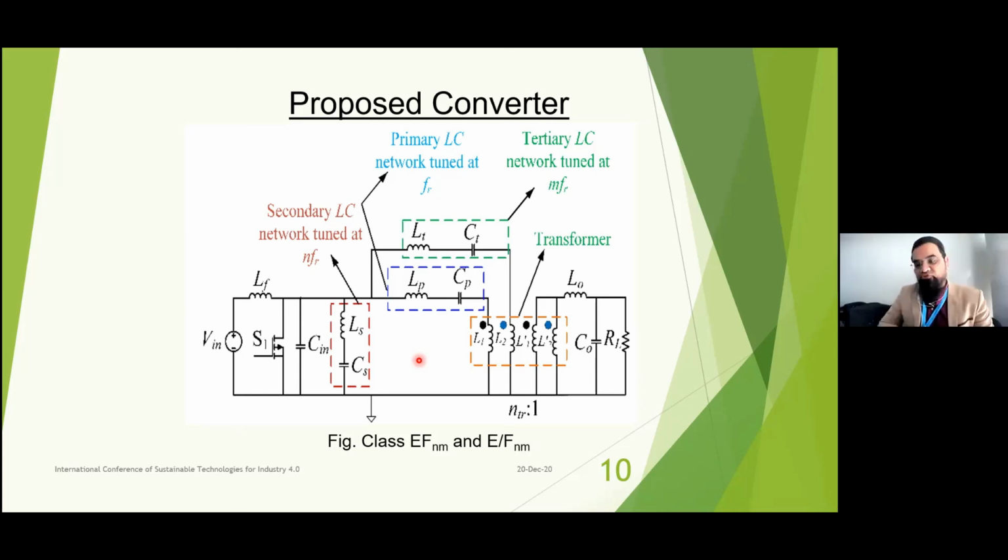Actually, the cutoff frequency here is around 100 kilohertz. If we plan to take the output as DC power, that will help us increase the total power output, and the filter circuit will eliminate the unwanted frequencies. Now there is a problem. If we apply the AC voltage, there will be some distortion. But if we use a rectifier and use the DC power, then there will not be any problem with the shape of the output waveform.